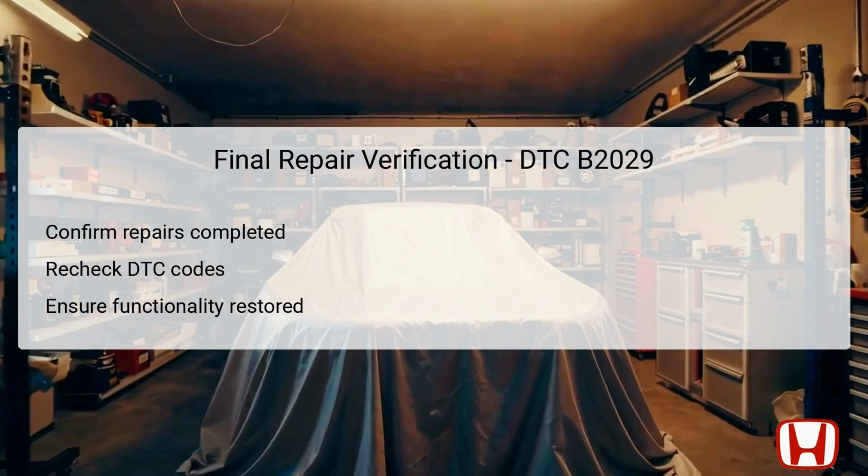After completing all the necessary troubleshooting and corrective measures for DTC B2029, it's critical to conduct a final verification of the repairs. This verification ensures that all issues have been addressed effectively and that the left power sliding door functions as intended. The technician should recheck for any diagnostic trouble codes, DTCs, using the Honda Diagnostic System, HDS, to confirm that the B2029 code has been resolved and that no new codes are present.